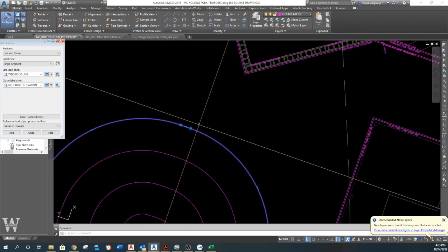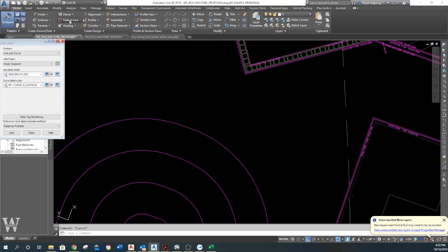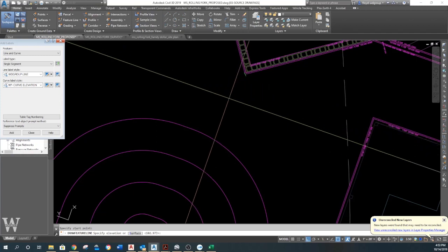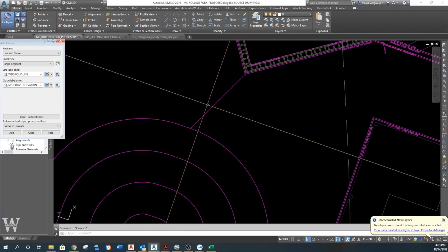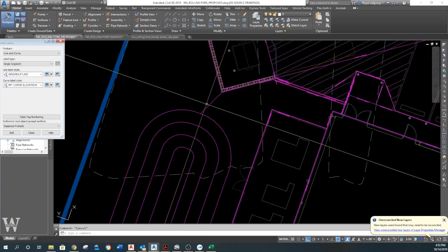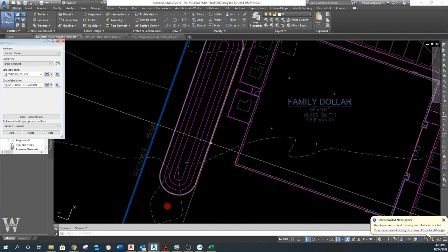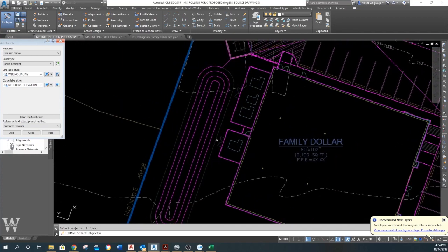And I'm going to break this at that point, and create a feature line from right there at 102 to right there at that elevation, which is 103. Okay, so all right, what that just told me is I don't want 103 as my top contour.